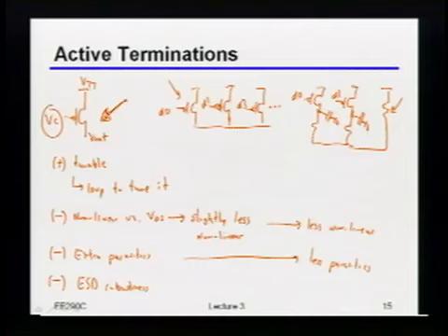Yeah, so in this kind of a tuning scheme, it's not linear, right? Well, it's linear in conductance, which obviously means that it's nonlinear in resistance. So when you do something like this, that's why I've drawn it in the digital version. Because in the digital version, it says something about the step sizes that you're taking, but as long as your maximum step size is sufficiently small, you may not care all that much. But then the individual resistances, some of them may be pretty large. Say that again? I mean, some of the resistances may be pretty large.